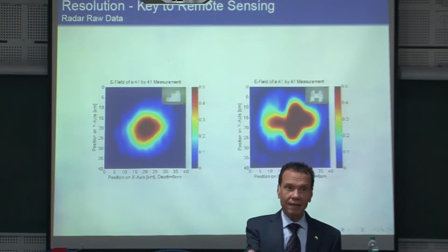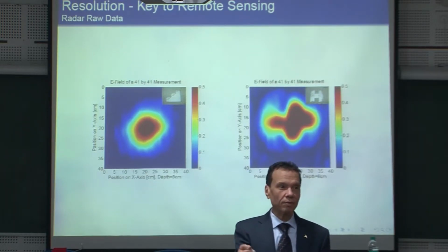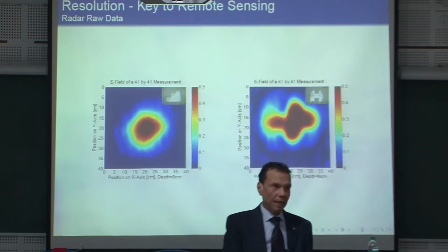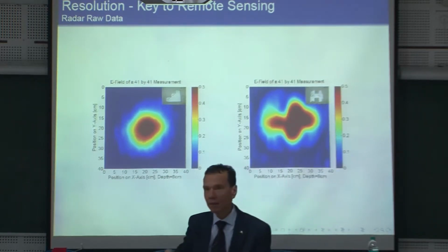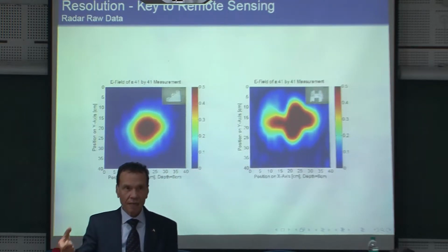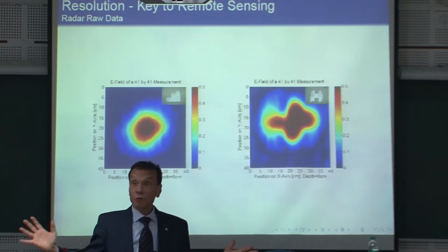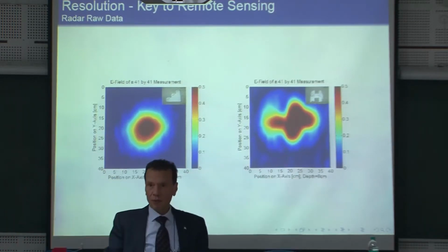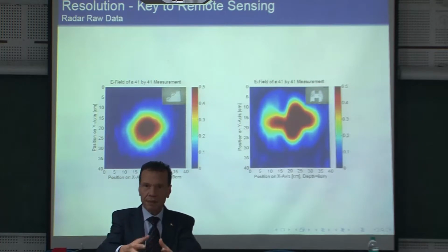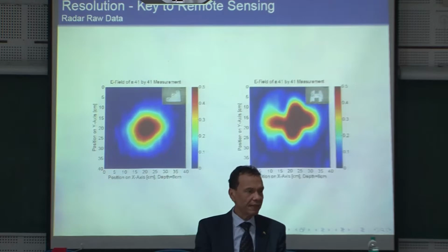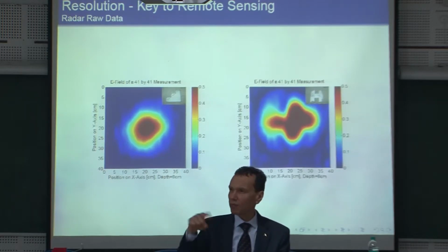Because, again, how have we conducted convolution? We said we take the point spread function as a torch lamp, okay, and go along the picture and consider the picture point by point, spot by spot. As if, instead of lighting the whole one, you focus the light into a spot and you go from point to point. And how have we got this? If you remember the relation between g hat and g by performing a Fourier transform.